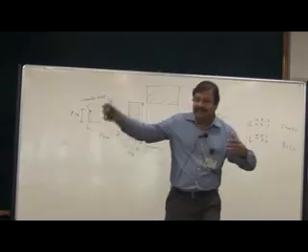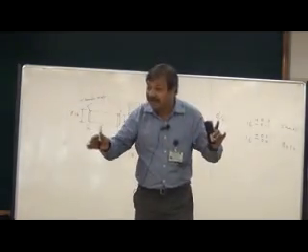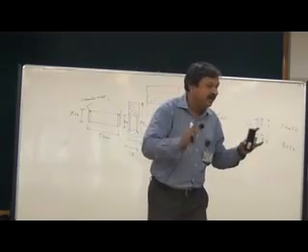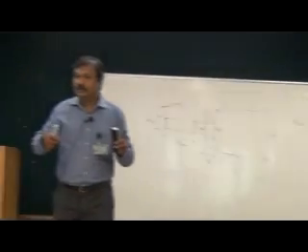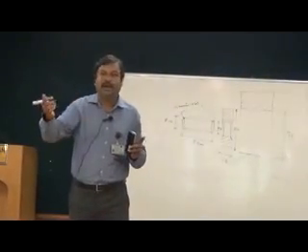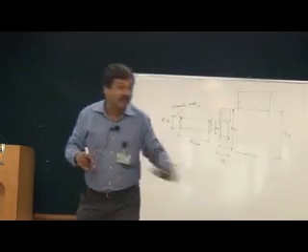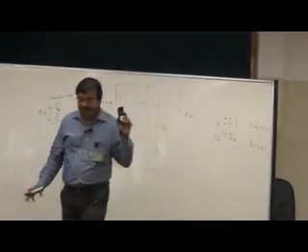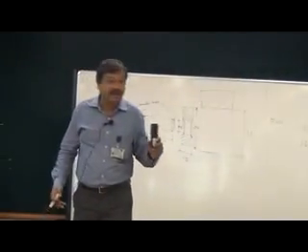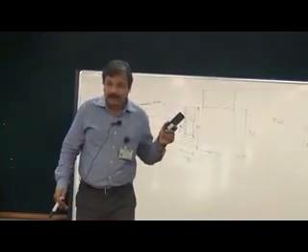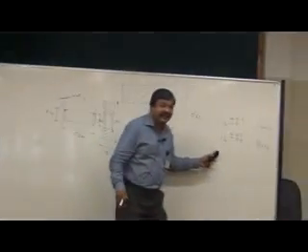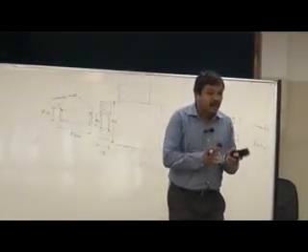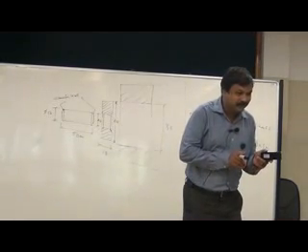When I take a shaft and assemble, there will always be a gap between the shaft and the hole. In the gap, you can put some lubricating oil, which will induce hydrodynamic lubrication, as you will study later. There will always be a gap, so it can run very freely. Accepted? Are you able to understand? By controlling the dimensions, that is the beauty of it.